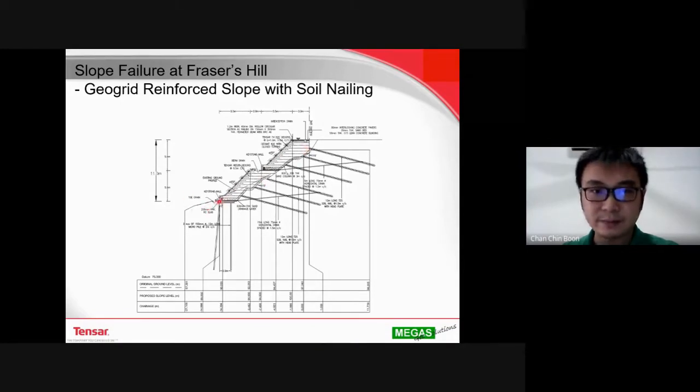And we provide some micropiles so that the load of this reinforced slope is able to transfer to a better ground below it without transferring further onto the slope. And the soil nailing behind is to provide a stability improvement or enhancement for a deeper circle at this line. Okay, so we give them back the platform. And this is the overall repair scheme that we propose.